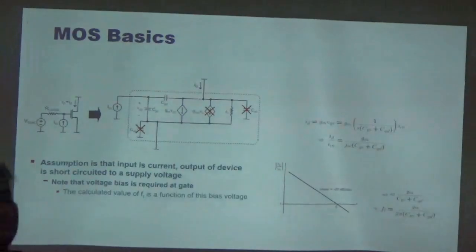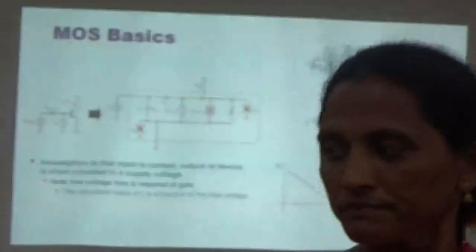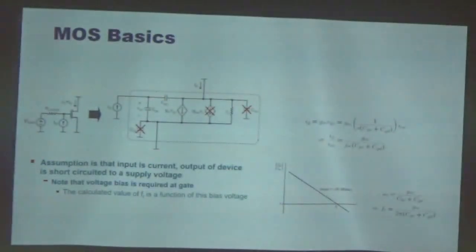If you go through the data sheet of any semiconductor technology, one of the major parameters already mentioned is fT and fmax. This is how we quantify how suitable the technology is for high speed applications. If you want to operate your design at very high frequencies, somewhere in 100 gigahertz, 200 gigahertz, then your fT and fmax should be almost 10 times or at least 5 times your operating frequency. This is a rule of thumb we can go for.